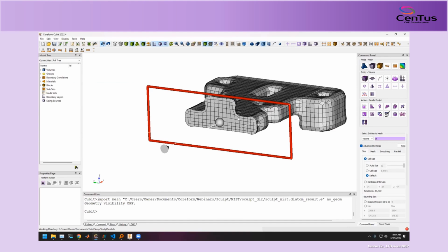So for traditional manufactured geometries, Sculpt often isn't a great solution for those kinds of models compared to, say, tetrahedral meshing, or what Coreform is producing, the Flex IGA approach, which is able to recover high performance nonlinear analyses. So I just wanted to demonstrate one of the side effects maybe of Sculpt for traditional manufactured parts.